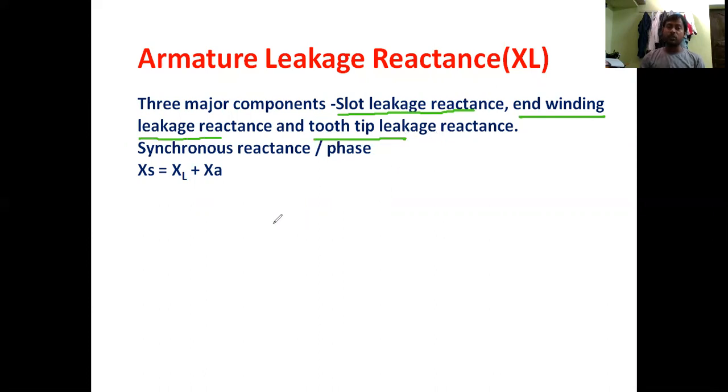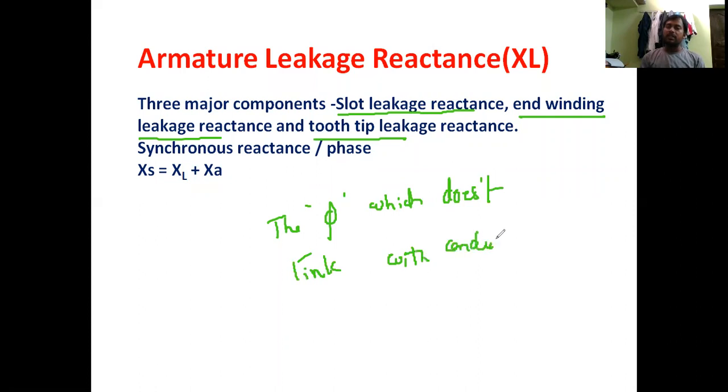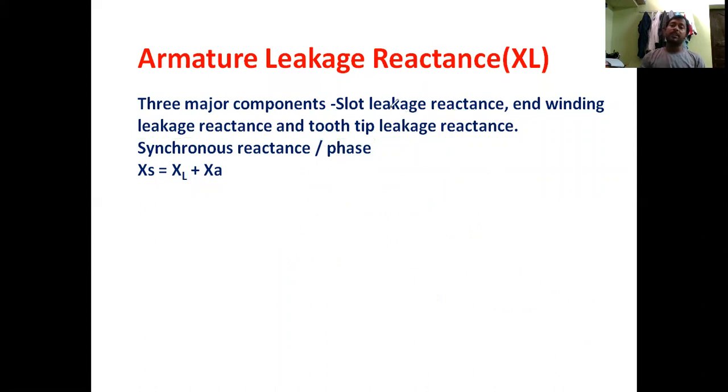Leakage reactance is nothing but, as I already told you, the flux which does not link with the conductor. Such a flux is called leakage reactance. That leakage reactance may be in any manner: slot leakage, end winding leakage, or tooth tip.